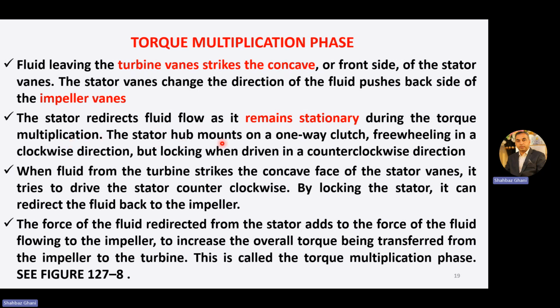The stator hub mounts on a one-way clutch, freewheeling in the clockwise direction but locking when driven in a counterclockwise direction. So in one direction it is freewheeling, and in the other direction it is locking. We will see this in our figure.